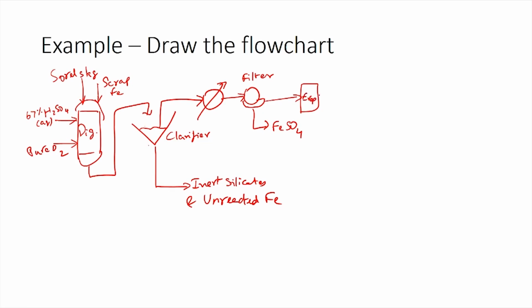What is given here is that this solution is then evaporated down to a slurry that contains 82% TiOSO4. Which means water is removed from the system. You have water leaving as water vapor, and you have a slurry which is then sent to a dryer from which you have the pure hydrate formed.